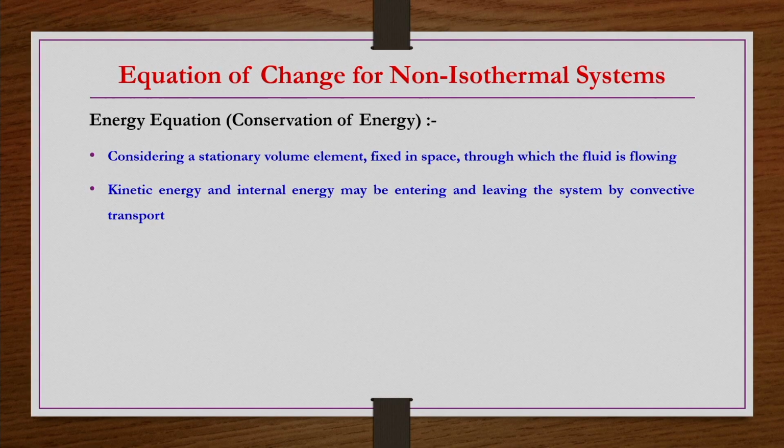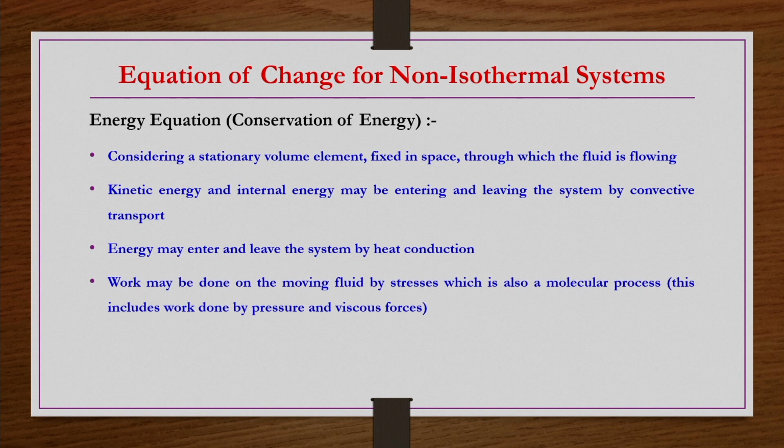Kinetic energy and internal energy may enter and leave the system by convective transport, and there may be energy entering and leaving by heat conduction, and there may be work done on the moving fluid by molecular stresses, that is, work done because of the pressure or because of the viscous forces. Those terms may also be included. And then there may be work done on the system by external forces. We are taking only gravity as of now.